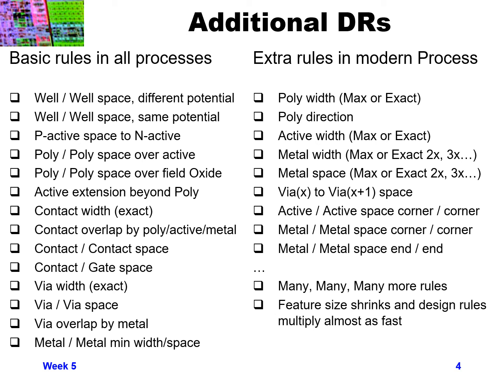The contact will need to overlap, in some cases, the poly, active, metal regions. You have spacing between contacts, and spacing between where you can make a contact and the gate. So if you're making a contact to your source drain regions, you'll need a certain space away from the gate in order to make the contact to the source drain region.